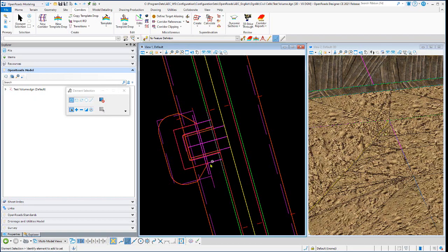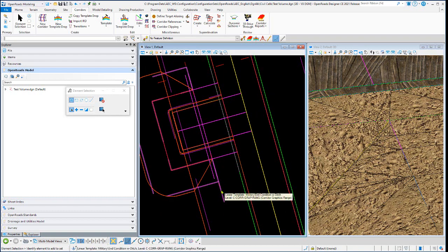Should there be a little issue, you do have the ability to just move this template back just a little bit. Put a tenth or something here, because I think ultimately what you could get at this point is the same elevation, right? So what I'm saying, this template may want to solve to existing ground instead of hitting this template right there at that point. So you may have to move it just a tenth or a hundredth this way. But I wouldn't here because everything looks good. You would rotate the view and see something. Same thing over here, right? Scoot this template back here just a little bit.